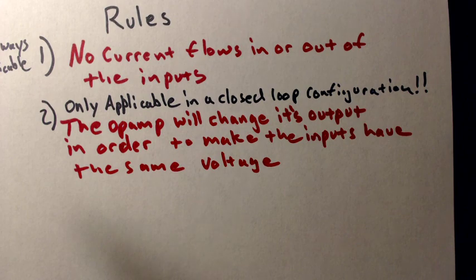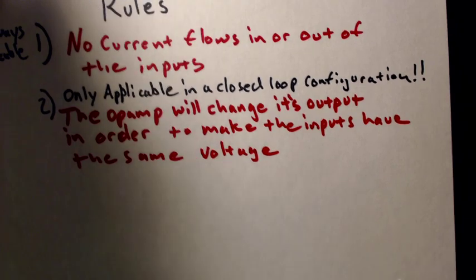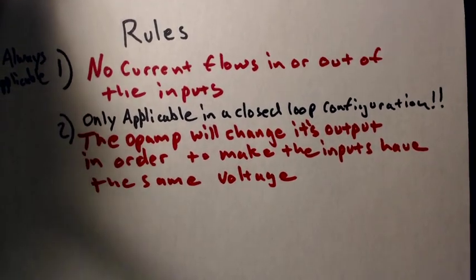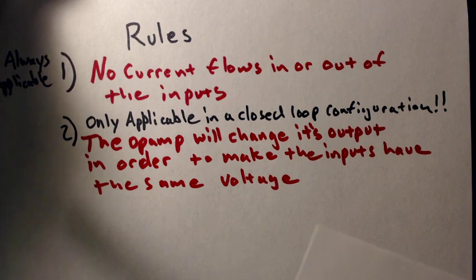Okay, the op amp will do whatever it has to in order to keep the inputs at the same voltage. Okay, this rule is what's going to make it super easy for us to analyze almost every op amp circuit that's out there. And so we're going to go ahead and show this rule with what I think is the most important and most often used circuit using an op amp.